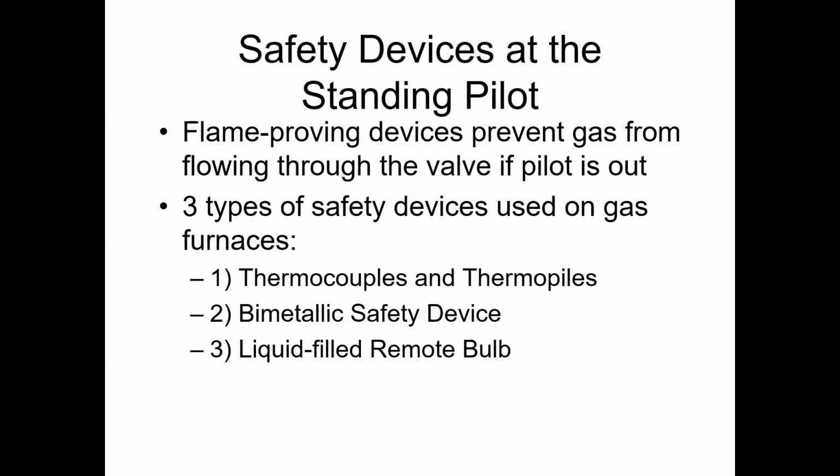And what I encourage you to do is take a step back, remember what we've gone over, think back on what you've seen in your books and in videos and everything, and try to just figure it out. How would this system work? If I've got a pilot and it's a standing flame, there's got to be some way that gas is getting to it, that ignition takes place, that it continues to feed gas to itself. And this is what all these different systems are going to be doing and what they're going to allow to take place. This is how a pilot is going to operate, by having these different flame sensing safety devices.